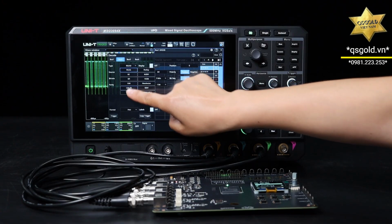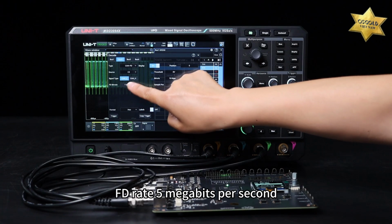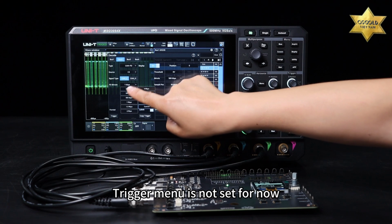Open the display. Select source as C3. Signal type CAN_L. Rate 500 kbps. FD rate 5 megabits per second. Sampling position is 75%. Trigger menu is not set for now.